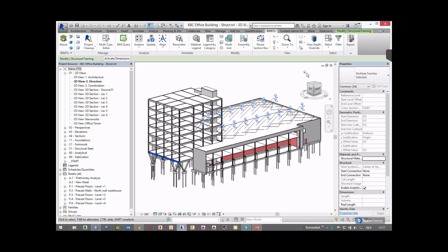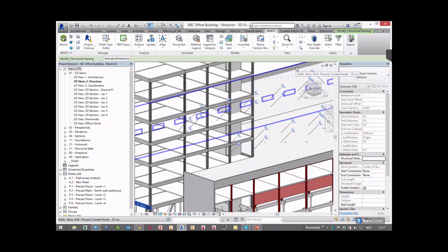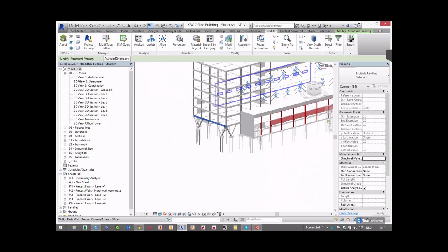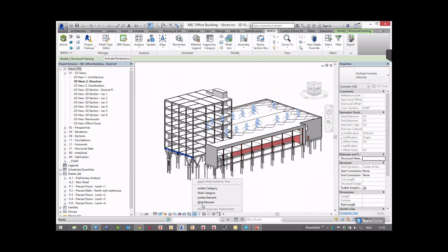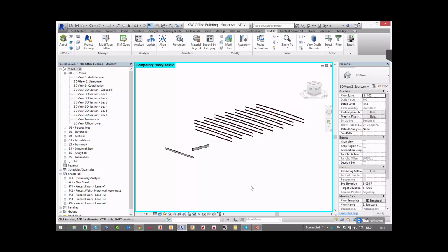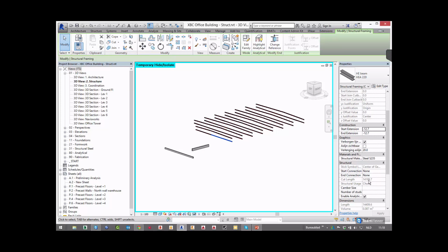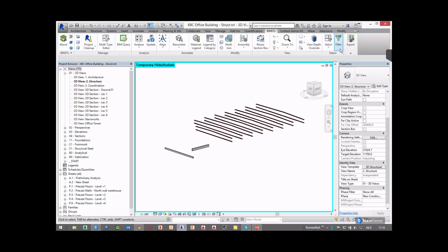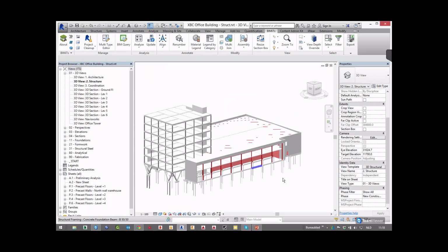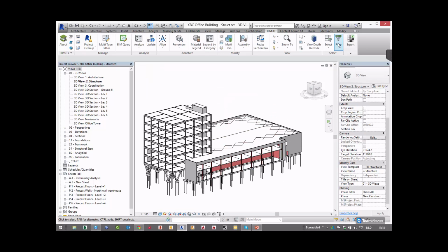And then you have options to, for example, zoom to selection. Well, and it zooms into that selection. So when I click on isolate element, here's a list of all the structural framings, based on category, that have a cut length bigger than 10 meters. Very easy tool to select on certain parameters.